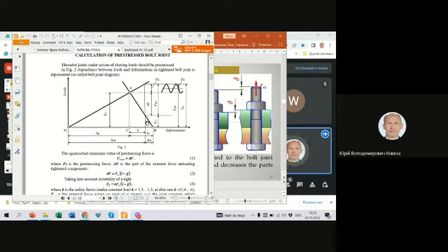In such case, we have deformation and we have remnant force, which guarantee this both deformation and force guarantee gap will not present. So we need to calculate prestressed force, which will be greater than delta F. Delta F is F external minus Fz.